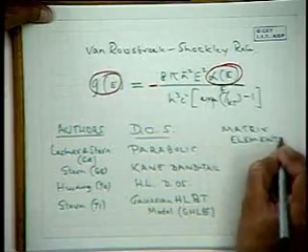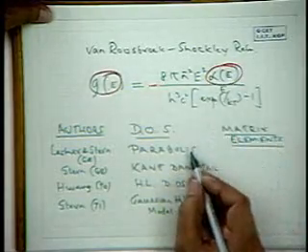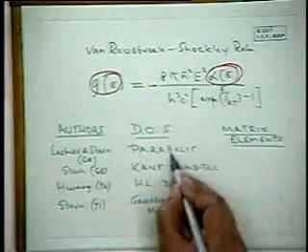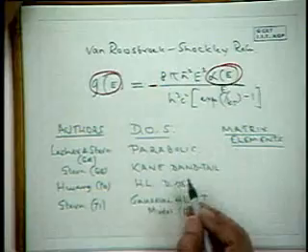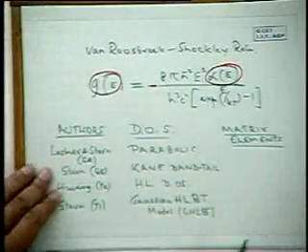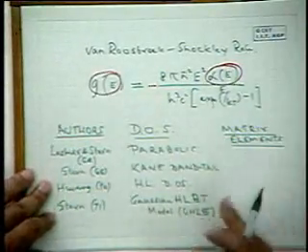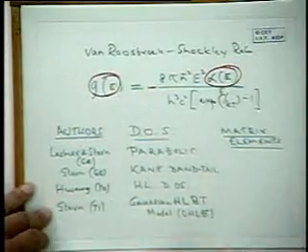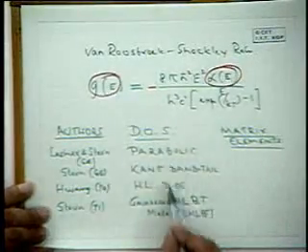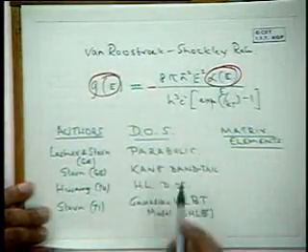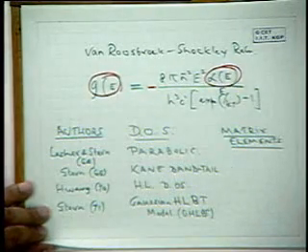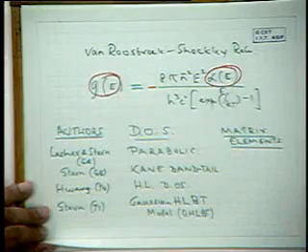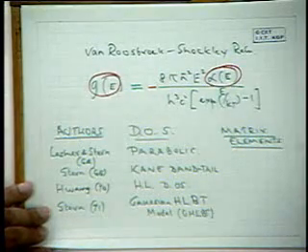For example, the simplest model, the parabolic band, if it agreed with the experiment, fine, then that would have been the end of the story. But physically, we are talking about highly doped materials, so heavy doping effects are coming in, band tailing is coming in. So in order to get agreement between theory and experiment, one has to introduce certain refinements into the band model. Okay.